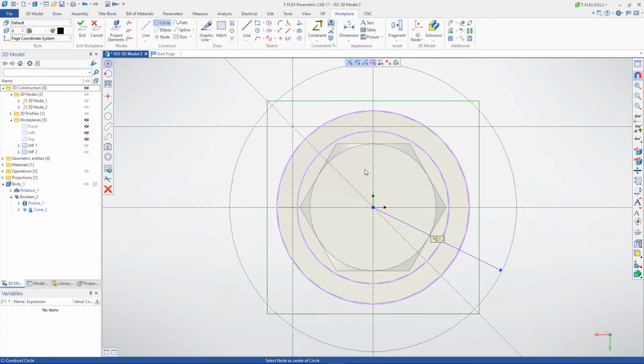Press enter. Select the intersection of two straight lines. Move the mouse to the already created circle. As a result, automatic tangency will be created. When we stroke the resulting skeleton with graphic lines, we need a circle on the projection lines, therefore, along the specified projection line, we also need to create a circle. We are now in the circle command mode, so just click on this graphic line.